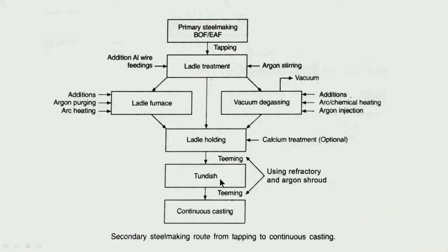Now, from the tundish, finally the liquid steel is allowed to move to the continuous casting mold. So, again the liquid steel will be coming out. Again at this stage of teeming there has to be a refractory shroud, which we call the submerged entry nozzle. The liquid steel is not allowed to fall just like that. There has to be a submerged entry nozzle, and there has to be some argon shrouding to protect the liquid stream, the stream of liquid steel, from getting oxidized and re-nitrogenized.